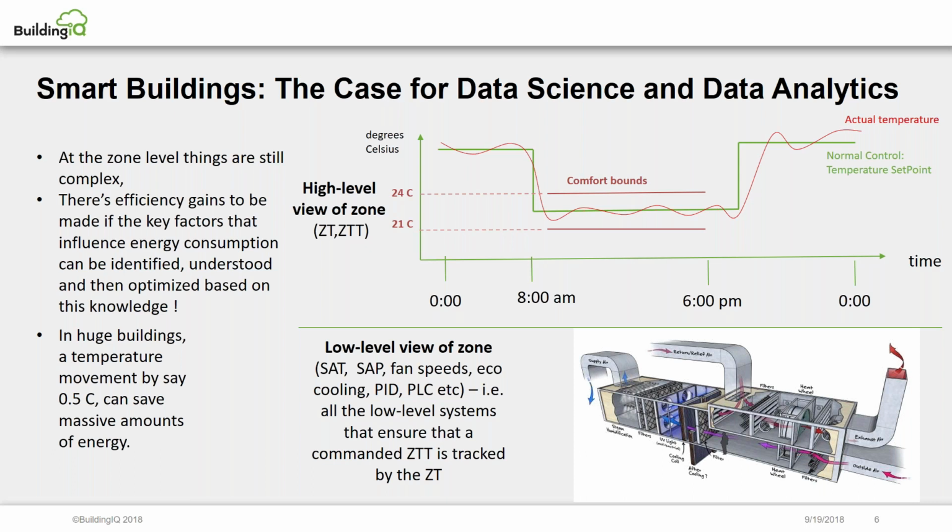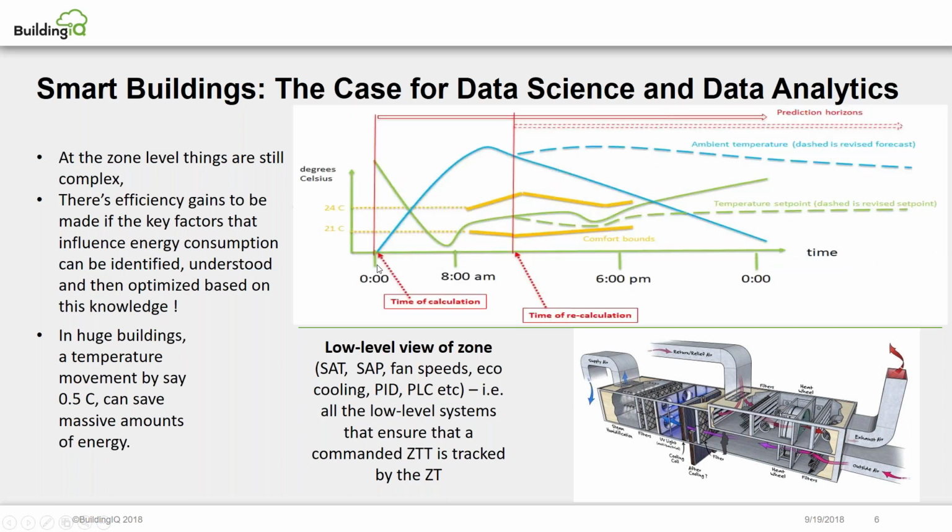So how we do it differently in terms of Building IQ, we have actually allowed the comfort bands, as you can see here, to be changing through the day. And we also change the temperature set points dynamically through the day. So the whole operation over here is kind of complicated. And those guys, the building operators, do a really good job in managing these huge mechanical systems.